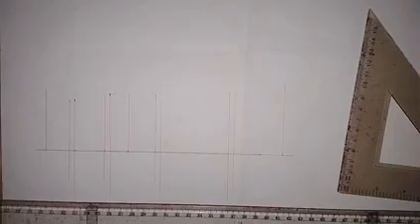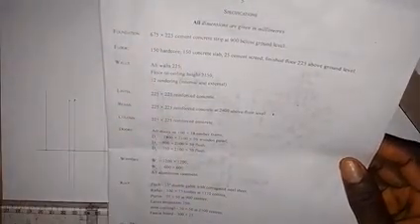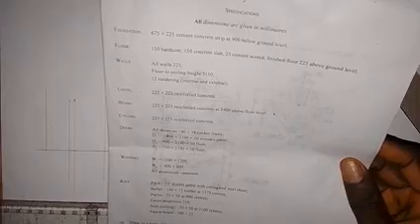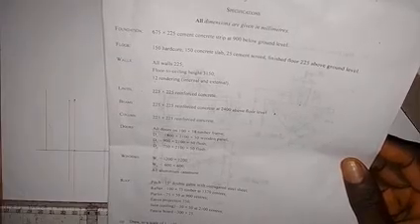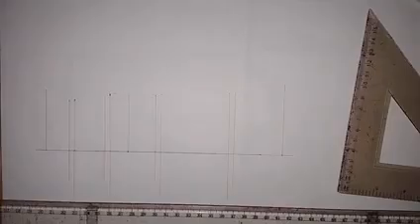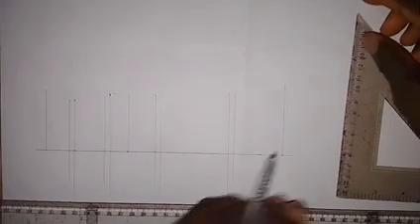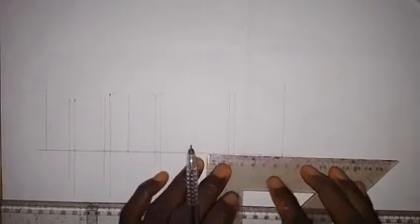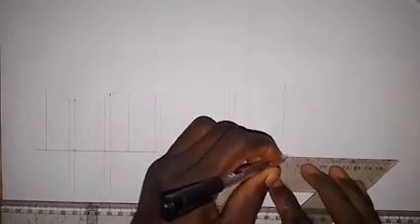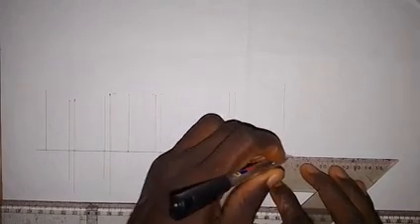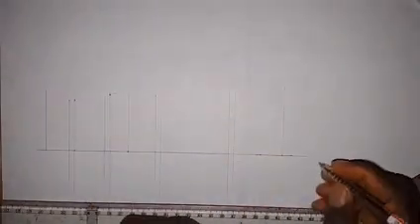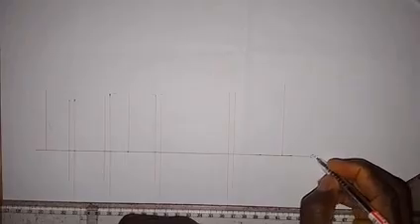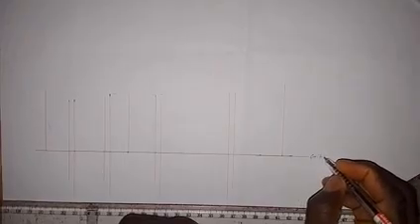The next thing that we are going to do is go to the foundation. For the foundation, we have a 675 by 225 cement concrete strip at 900 below the ground level. Do not forget that this line here is the ground level, so I need to indicate that. So this is the ground level line, and we indicate that with GL.